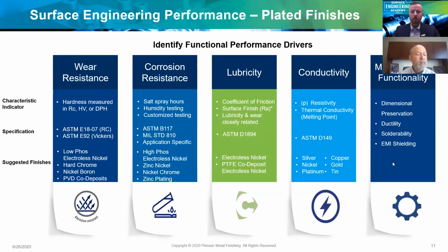And again, plating such as tin does a very good job for solderability. Nickel platings, both Electroless and electrolytic, do a great job of EMI shielding. Yeah, really a whole host of miscellaneous or specialty performance variables that various platings can offer. Don't have time to get into all of them, but certainly some of the more common ones here listed.